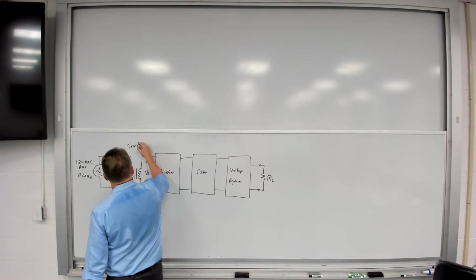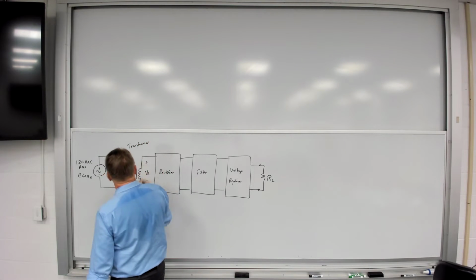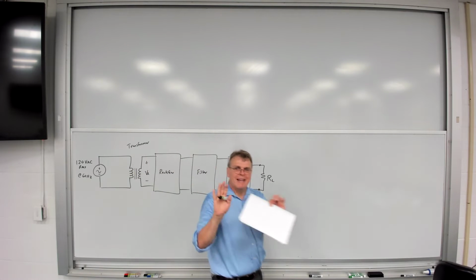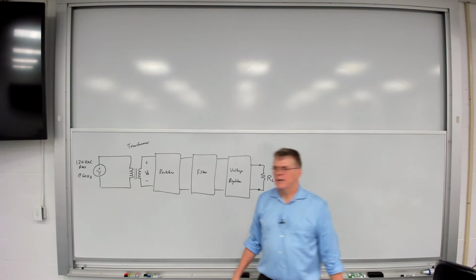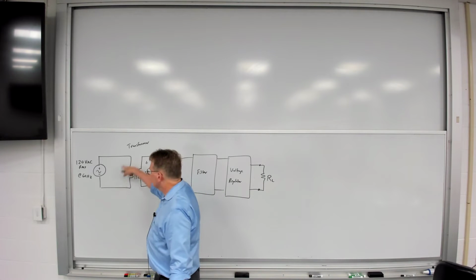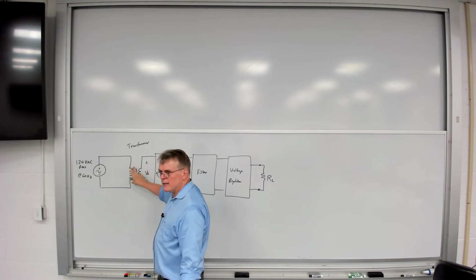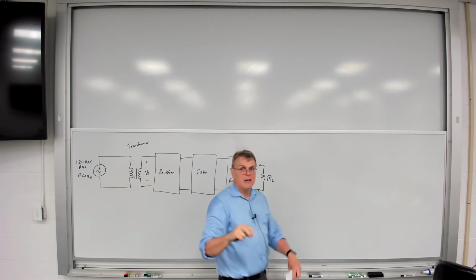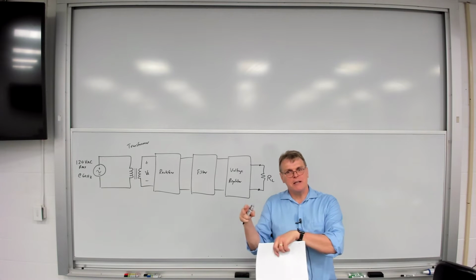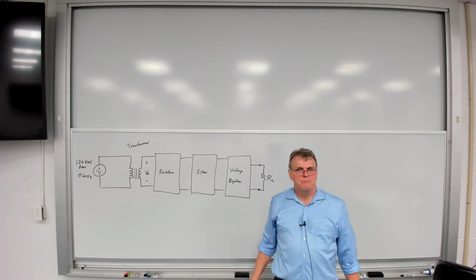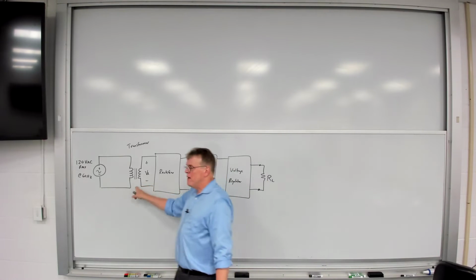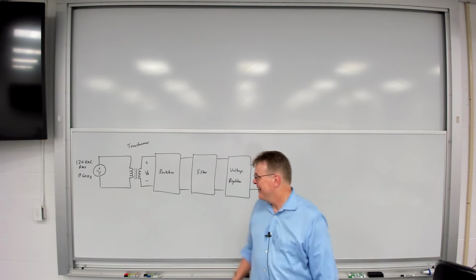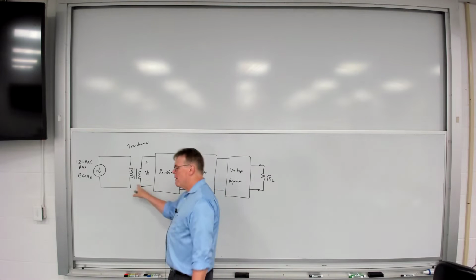And we're not going to cover the transformer in this class, but I'll briefly tell you that this is nothing more than a device where you're magnetically coupling two inductors. And so the voltage in this inductor induces a magnetic field, which couples into an inductor of a different size, and it will then induce another AC voltage, but of a different amplitude. So this is used very much in modern power transmission and distribution. Not really used so much now in modern power supplies.